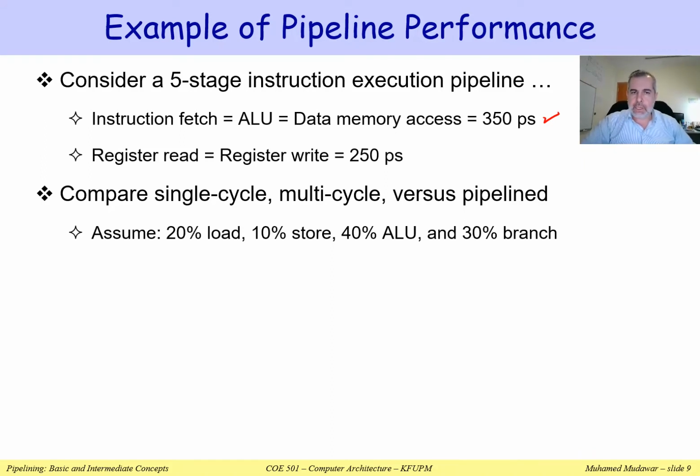The same thing for executing. So this is the delay for the instruction fetch. The same thing, the delay in the ALU, and the same thing, the delay in the data memory access in the data cache, is 350 picoseconds. So this is how it's given. Of course, circuit designers have to look at the real delays inside these components, inside these different stages of the pipeline. It says that the register read and the register write take only 250 picoseconds. So to access the register file, it only takes 250 picoseconds. Of course, the numbers might be different according to the technology which is being used.